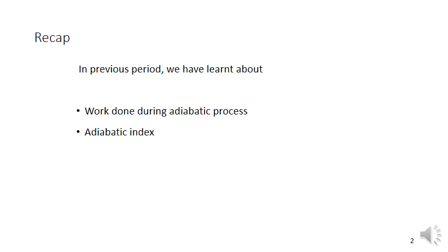Non-flow energy equation: dQ is equal to dU plus dW, and dQ is equal to 0. So dU plus dW is equal to 0, then dW is equal to minus dU. So here, during the expansion process, the internal energy is decreasing. In compression, the internal energy is increasing.